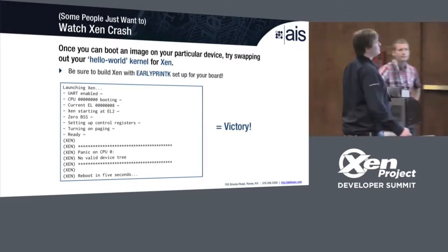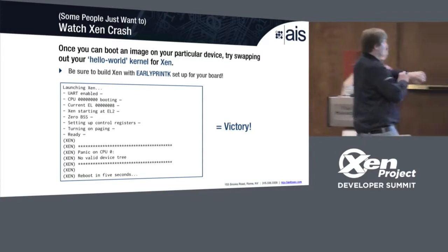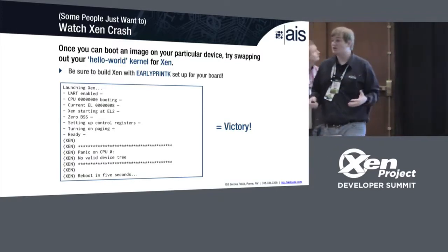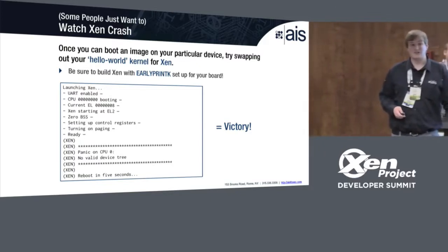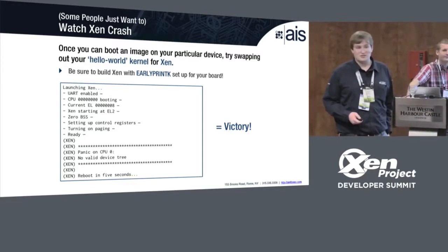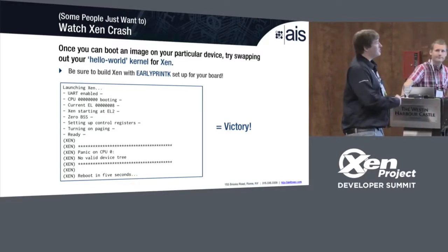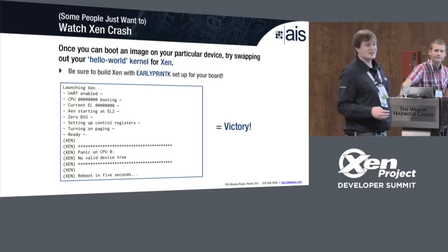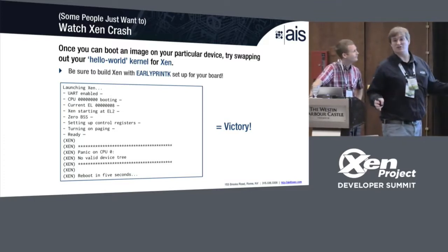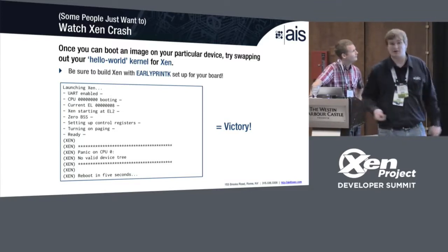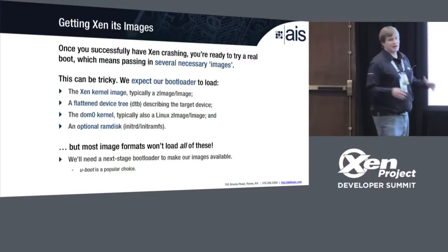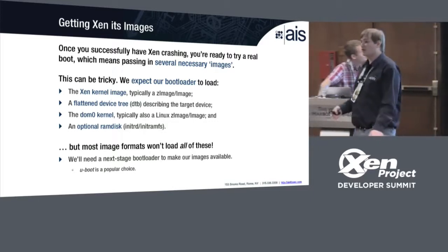I had some interesting challenges trying to get our Pixel C up and running, even just to get Xen to boot, because one of the things the Pixel C bootloader did not like doing was telling me where it put the TrustZone secure world. So there's a whole region of memory that it was not telling me about, where if I wrote, the accesses were just denied, right, silently, and I wound up writing basically zeros into these registers with no other visual outward appearance of anything but success. So that's interesting.